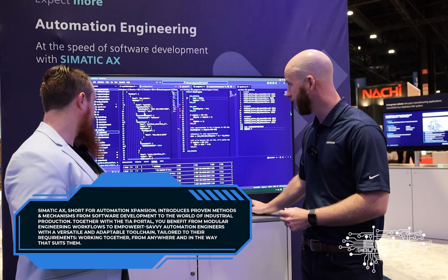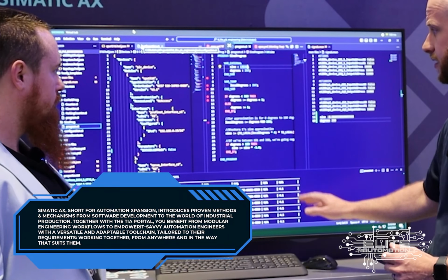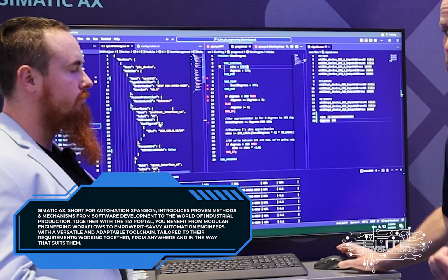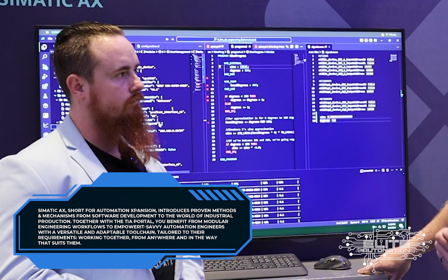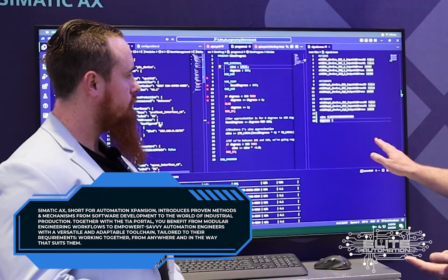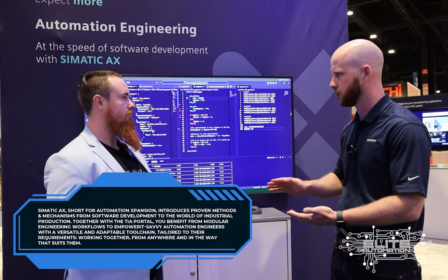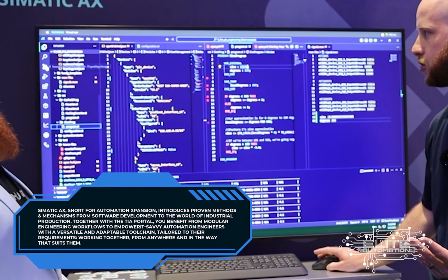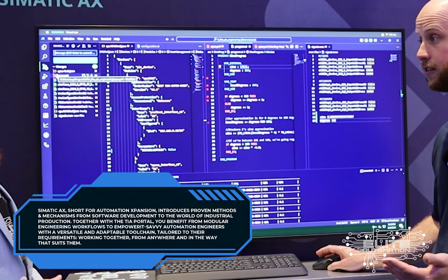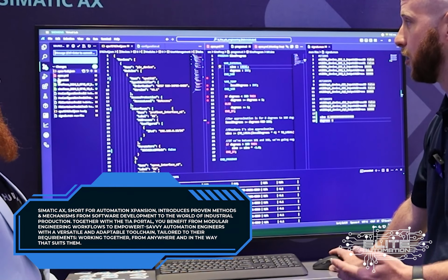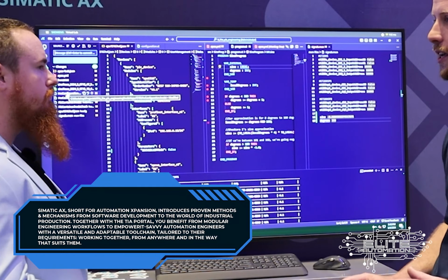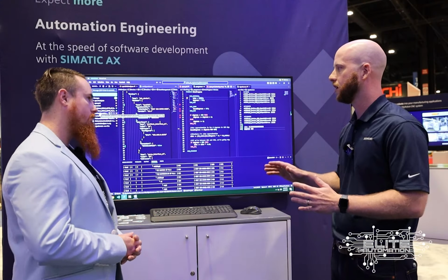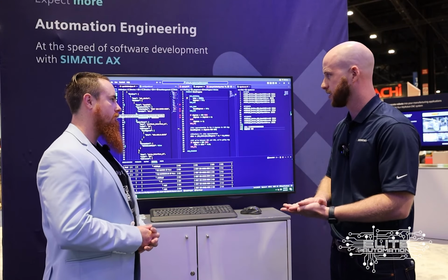So everything is text-based within this platform, so you can program your PLC. But even from the hardware configuration and software side of things, monitoring, diagnostics, a lot of configuration files are just strictly text-based. So what does that mean? We're going to be able to source control very easily. We have native Git integration here as well. Okay. So again, a big topic here this week has just been how do I do change tracking over time with this? So that has been a big plus.